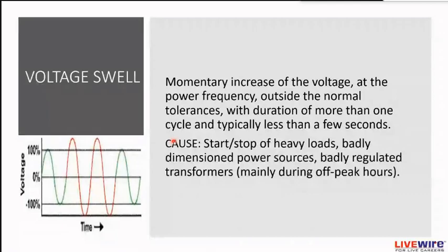So what are the causes of this voltage swell? The start and stop of heavy loads and badly dimensioned power sources will cause the voltage swell. The consequences of the voltage swell are flickering of the lights, and damage to sensitive equipment and so on will occur during the voltage swell.